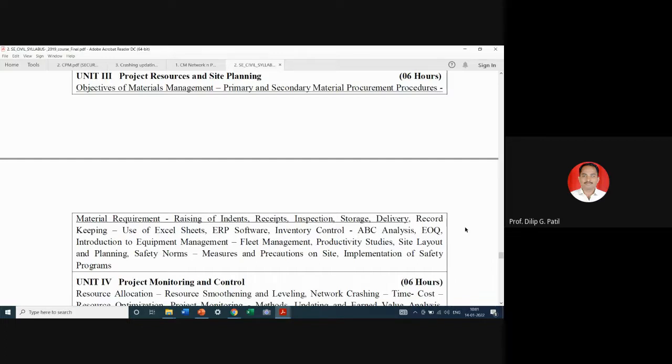So accordingly, we have to order the required material in batches, so that the flow of material is such that there will not be any obstruction or deficiency to the ongoing work, but it should not be too much, which will increase the inventory carrying cost also, because we need to take care of materials from many parameters like environment, and from elements like corrosion or deterioration.